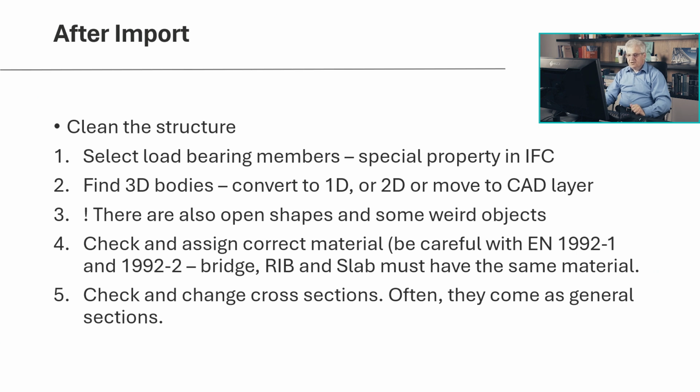After the import, you have to do some steps, and we can look at it in our model. You get a lot of trash, usually, in the IFC file. You see the flowers, you see the furniture in the rooms, you see the Mercedes in the garage. I don't know why they draw every time only Mercedes in the garage, but there is every time a Mercedes there. So you have to delete them or keep them on some layer which you don't need. But usually I delete everything.